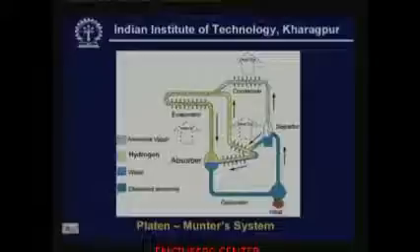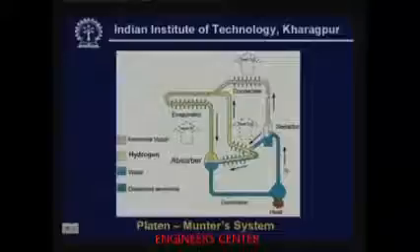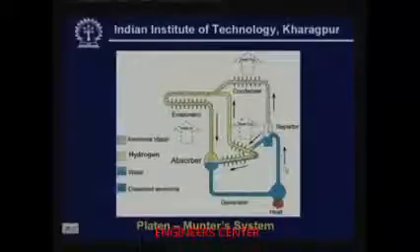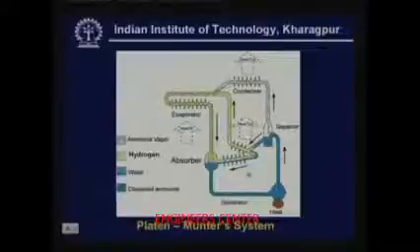And here you can see that the major input is in the form of heat only, and here we use a component called a bubble pump for pumping the solution from a low level to a high level. And these systems have many advantages. For example, since you don't have any mechanical component here, they are extremely reliable, and they are also silent in operation. That is the reason why these systems are typically used in small domestic refrigerators, in hotel rooms, etc., where you need silent operation. So the use of these systems is mainly confined to these kinds of applications. However, they are not used in large systems because their efficiency is typically very low.